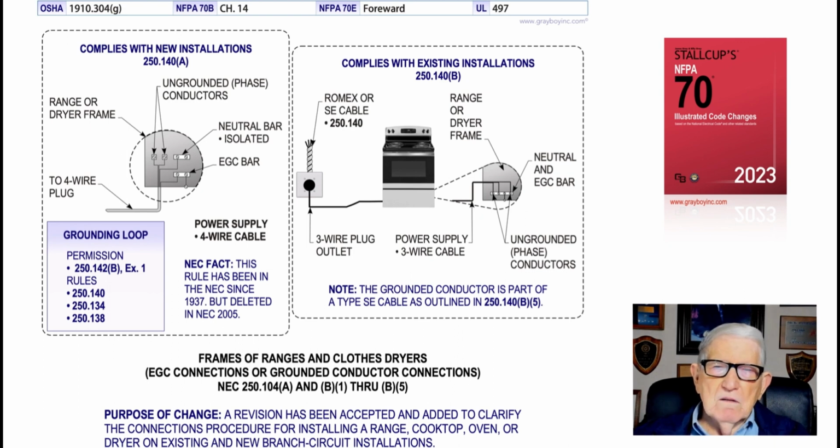So just to go through this in a paraphrased procedure, the panel to the left, we have a 150 amp overcurrent device, and according to Table 250.122 on page 158 approximately of your code book, you would need a number 6 grounding or equipment grounding conductor pulled through that raceway.